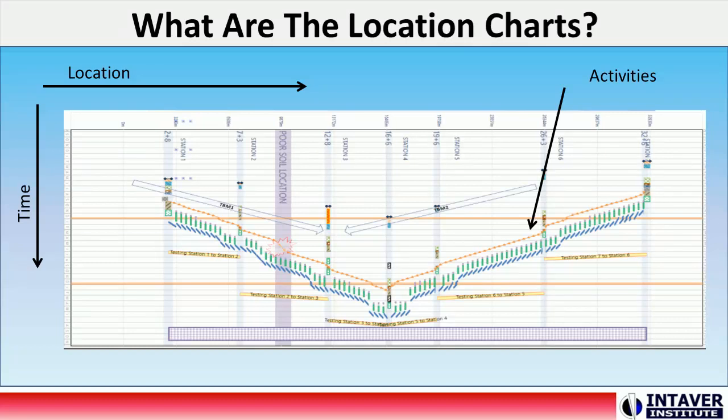Traditional representations of a schedule for a high-rise building project use Gantt or bar charts, with time on one axis and a form of the work breakdown structure on the other. Location-based scheduling allocates quantities to the locations and takes into consideration resourcing required to complete these works, including production rates, crew sizing, logic between tasks, and any requirements for splitting or buffering works. This technique allows managers to identify potential risks that can arise due to complexities from on-site work conflicts, resource constraints, and other issues.